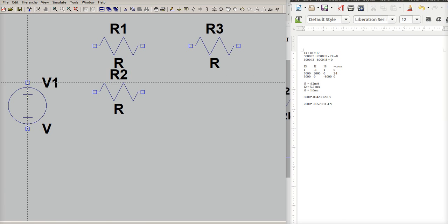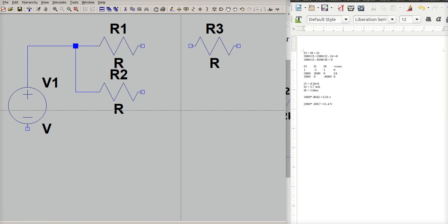Okay, so I'm going to go vertically here until I see my line intersecting with the box to the right that I want, and then I'm going to click, and that allows me to turn corners. And when I get to the end box, I click again and I have a line. For this one, I'm going to click, and I'm going to go left slightly, click, and then I'm going to go up until I'm back in that other wire, and it will put a node in there for me.